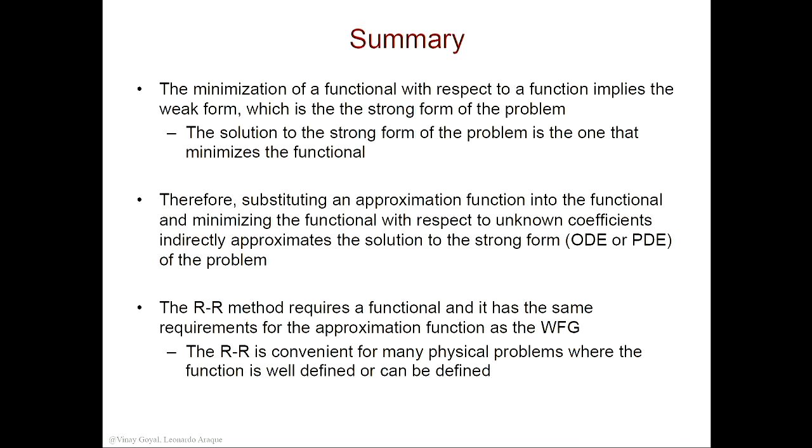Finally, in summary, this is my last slide. The minimization of the total potential energy, which in this case is a functional because it depends on a function, is basically the weak form. We showed you that minimizing the total potential energy, or the functional, gives you a weak form that corresponds to a strong form.